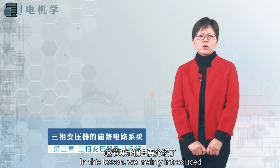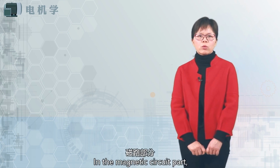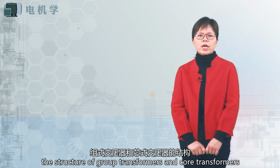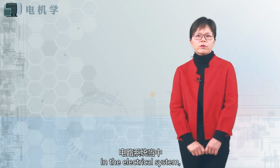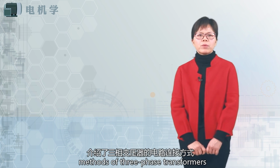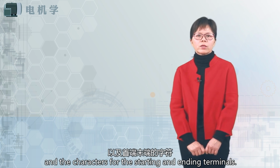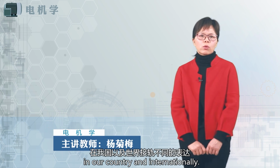In this lesson, we mainly introduced the magnetic circuit system and electrical system of three-phase transformers. In the magnetic circuit part, we mainly introduced the structure of group transformers and core transformers and compared their characteristics. In the electrical system, we introduced the circuit connection methods of three-phase transformers and the characters for the starting and ending terminals. We also introduced the different expressions in our country and internationally.